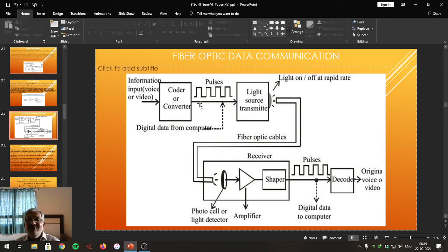If signal is 0, carrier wave amplitude is 0. ASK is also called as on-off type of keying. Within a bit period, according to how many pulses are passed, the carrier wave amplitude is changed. And that signal is given to the light source or transmitter.